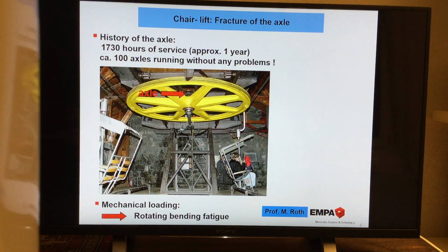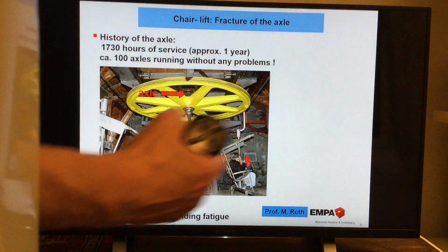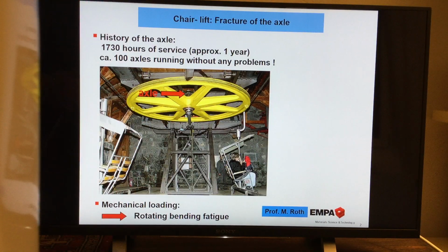It's very important. For those who are really experts in mechanics, I have to tell you, when the machine starts, in the first seconds, until it's really running continuously, there is a torsional moment on that, but this stabilizes after a while when we have continuous movement. So this is very important all the time, that we think about the mechanical loading of this component.